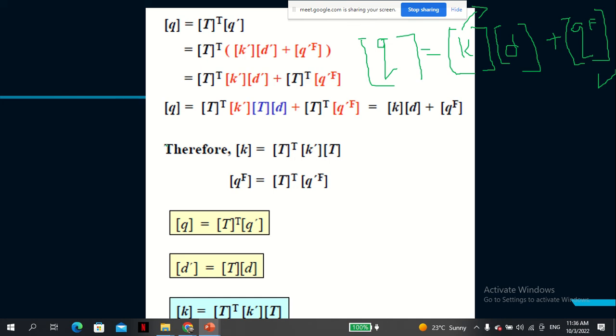support condition. For example, you know that in a fixed support, not fixed support, sorry, for a pin end, the moment is 0, and displacement, we cannot have any displacement, is 0. So using these boundary conditions, then you're able to solve. I'll demonstrate to you shortly. You're able to solve your problem. So this is also key. This formula is key, but needs some keen consideration.